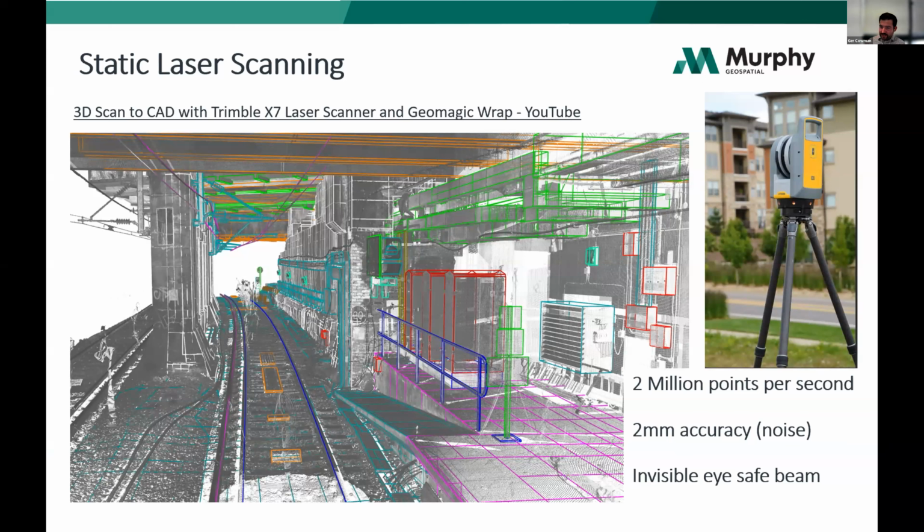You can see here that the different colorization of the gray point cloud really emphasizes the different aspects. And what I meant before is we could fully capture a rail line like this and draft everything, but really all that might be required is the location of the four orange pits down the center of the rail line there. So a better understanding of what's actually needed can save time and money by better understanding what the end use application is.